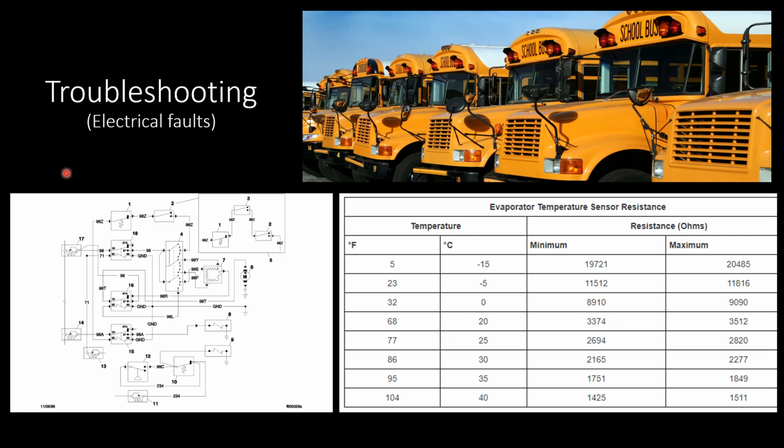So when it comes to the electrical part of it, you're going to have to kind of start all over, right? You've already verified the complaint. Now you're on step number 2 again, and that's looking up all the information, and then you're going to start going downstream and seeing where you're not getting signal, or if it's the sensor that has failed. Pretty much you're starting over, troubleshooting completely from step 2, and you're going to start looking at electrical system faults. Now, if you guys want to learn more about troubleshooting electrical, Alex's class is definitely one to take. If you have the opportunity to take it today, take it today.